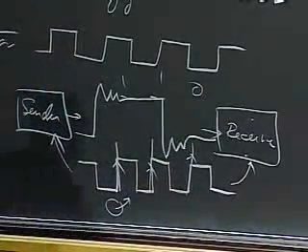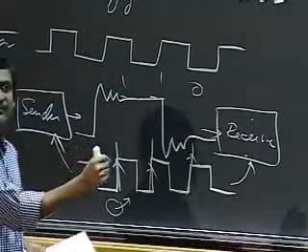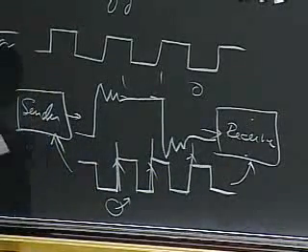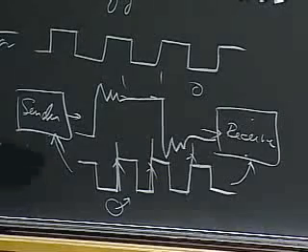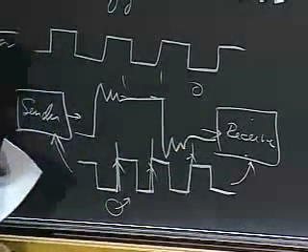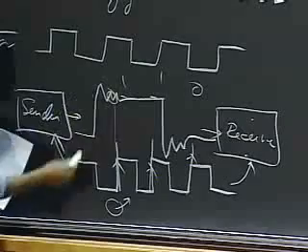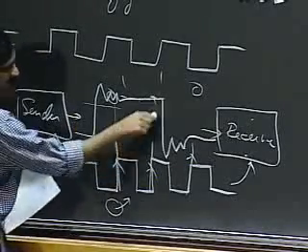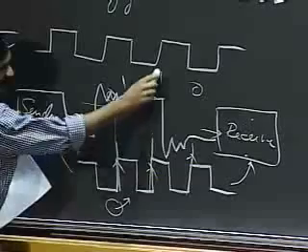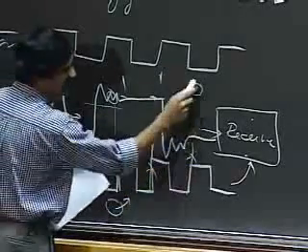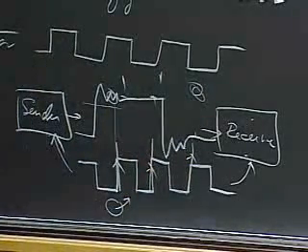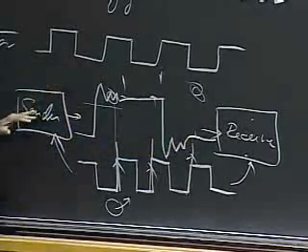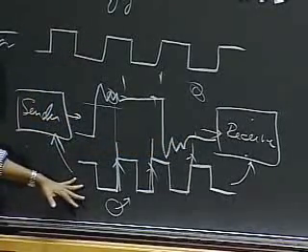Whenever the clock rises, whenever you see a rising edge, look at the value on the wire, and that's the value I sent. Okay? So by doing so, the receiver can look at the signal. At this rising edge, it sees a 0, if this is VOH. Looks up here, sees a 1 here, sees a 1 here, and sees a 0. So it correctly samples 1, 1, 0 at the receiving end, and the sender can send the same sequence here once we have this time base.